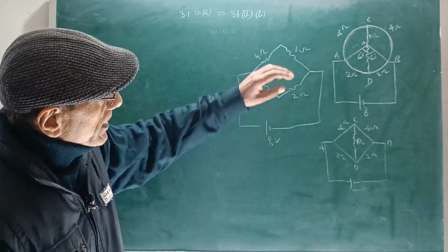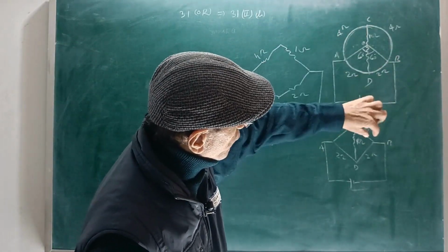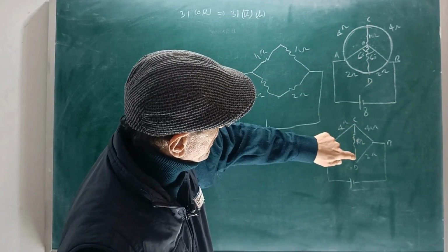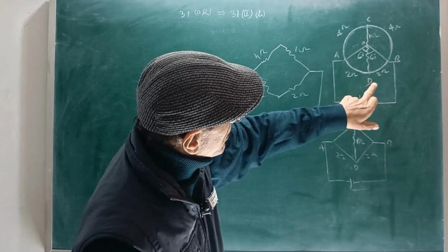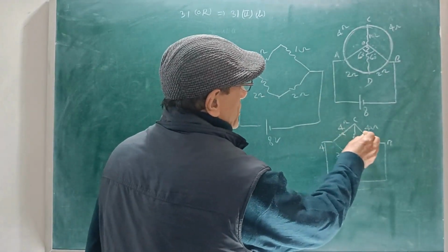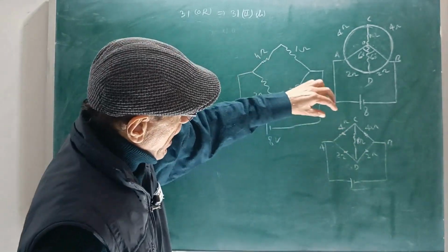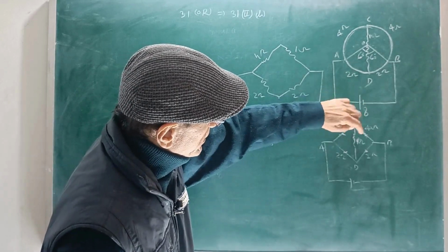फिर से देखिए, ये 4 ओम है, ये 4 ओम है, तो ये 4 हमने लगा दिया, यहाँ 4 हो गया, C पॉइंट है, C से D पॉइंट हमने यहाँ बनाया, यहाँ 10 ओम का रेजिस्टेंस लगा हुआ है, A से D पे जो है 2 ओम का है, और D से B के 2 ओम का है. इसमें आप रेजिस्टेंस ऐसे शो कर सकते हैं, कोई इश्यू नहीं है, और वायर लिखा है, वायर था, इसे मैंने वायर ही बना दिया. अब Wheatstone bridge की कंडीशन बन गई, तो this by this equal to this by this,